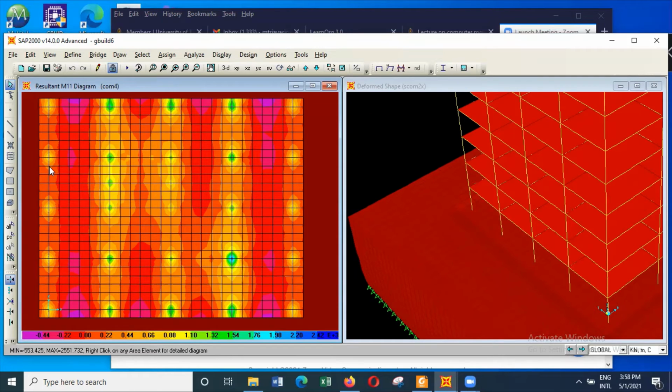Loose sand cannot give a bearing capacity in the range of 150, and only a stronger sand, dense sand, can give that kind of bearing capacity. So basically we are having a weaker soil and we are getting these results.